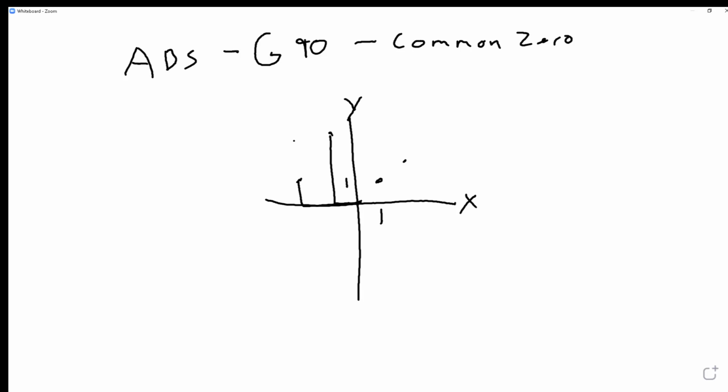Now, incremental means that essentially you restart each time. So I'm just going to clear screen here. Incremental programming means that if this is our Cartesian system right here, and this is the first point and this is the second, it comes from 0 on the first point, but the coordinates re-zero from where you are.